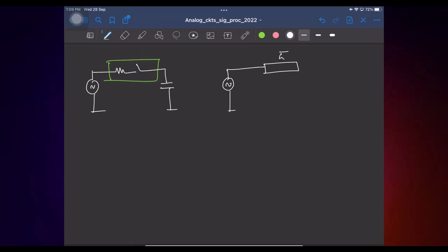I'll say this is a G matrix. Similarly, I have a constant capacitor. I know the admittance matrix for the capacitor. And let us say you are interested in finding Hk of J2 pi f. What is the input you will apply? e power J2 pi ft.